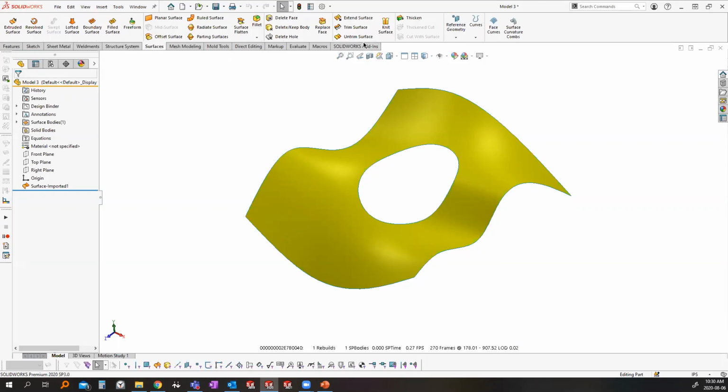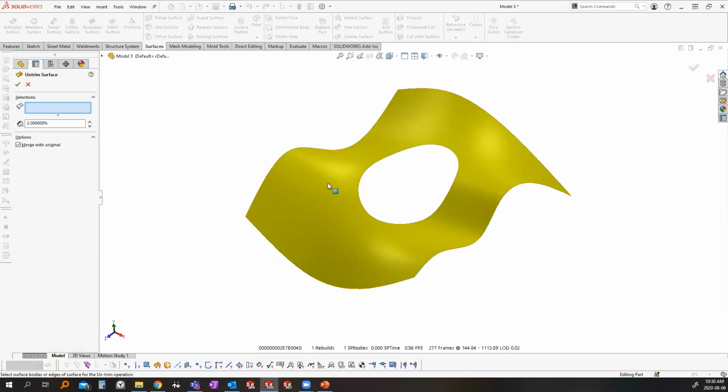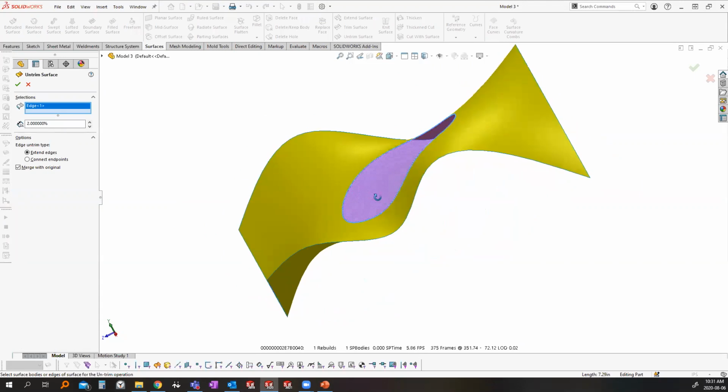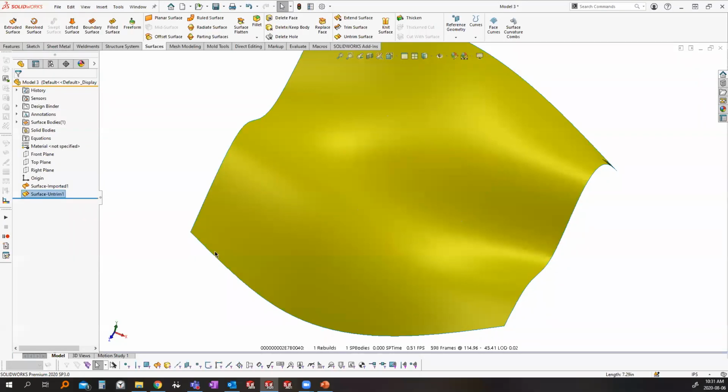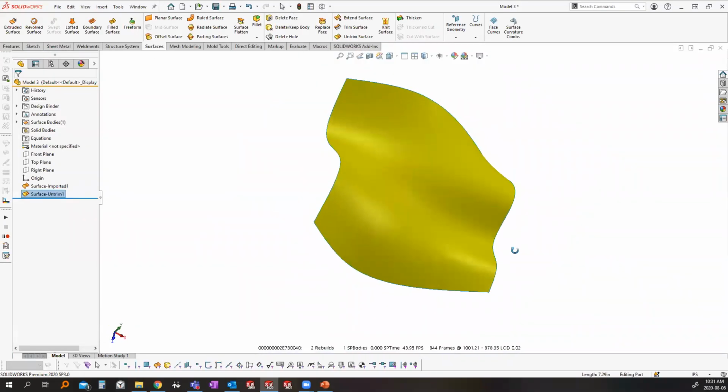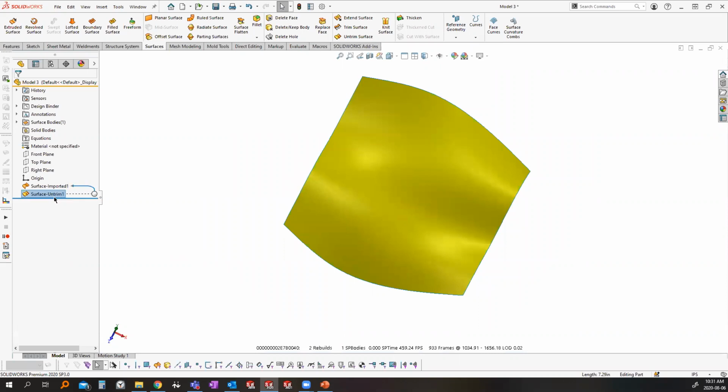are something like untrim. What it does is brings back that underlying geometry. So it's imported. I don't have a feature tree to work with, but you can see it just naturally kind of remembers those surfaces. And we're back to a fully restored complex surface.